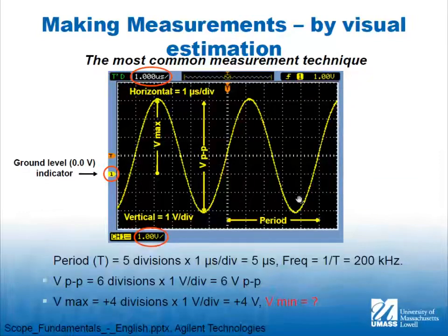And that's going to allow me to display this signal. But the other thing that's going on here is the fact that I've been storing all of these signals in a circular buffer. So it says start displaying here, but it's also going to display everything it had in the buffer that led up to that point. So when we do logic analysis, and you know, in simulation, there's ultimate controllability and observability, but in logic analysis, we generally don't want to see what comes after an event. We want to see what led up to the event.